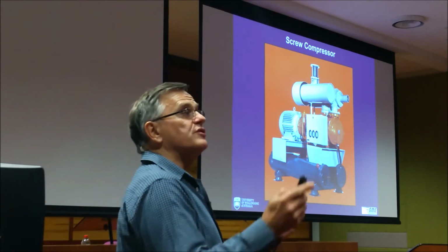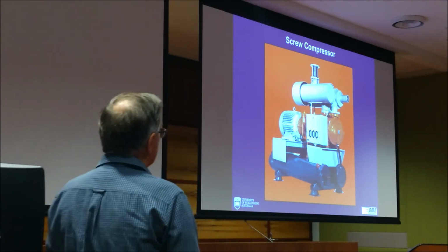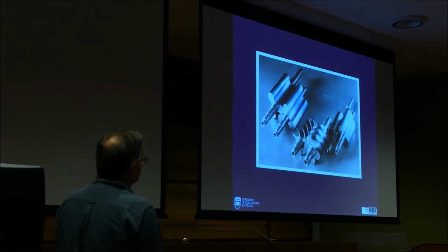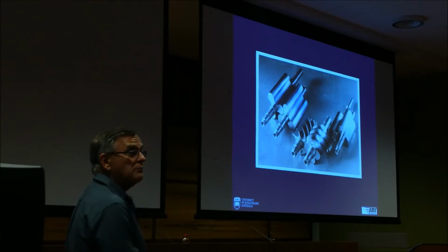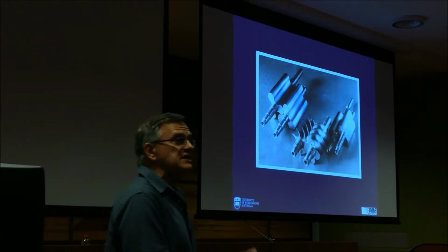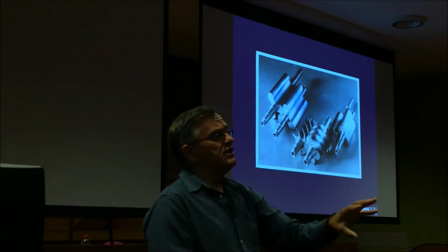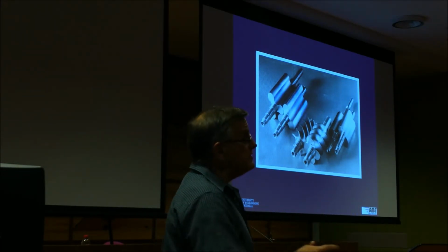The main difference is what you see inside the element. Here we see the traditional 2-lobe blower, and the more recent 3-lobe blower. They're positive displacement devices. They only capture a pocket of air and discharge it. They don't compress the air before they discharge.